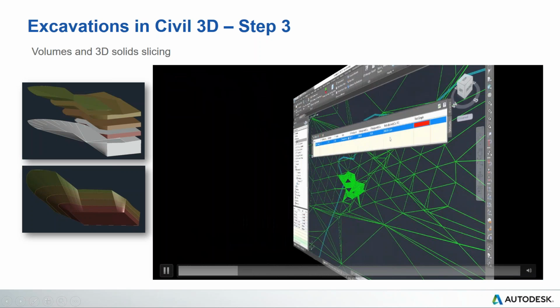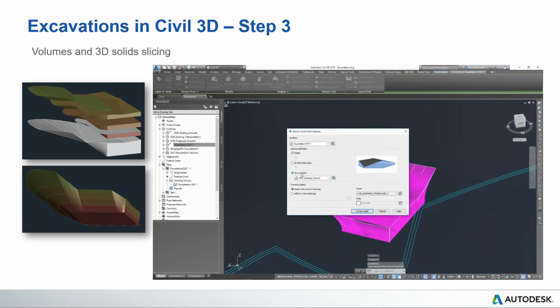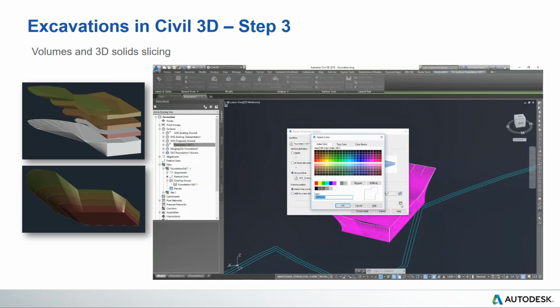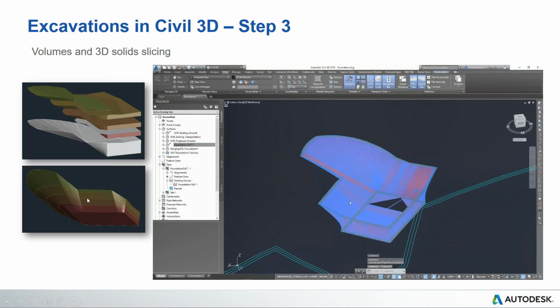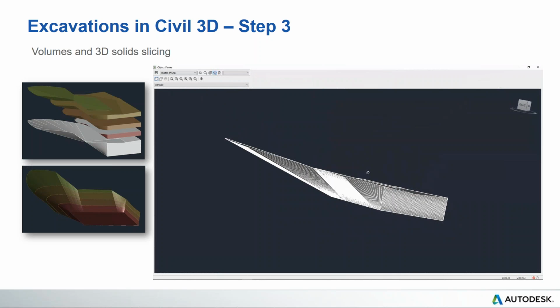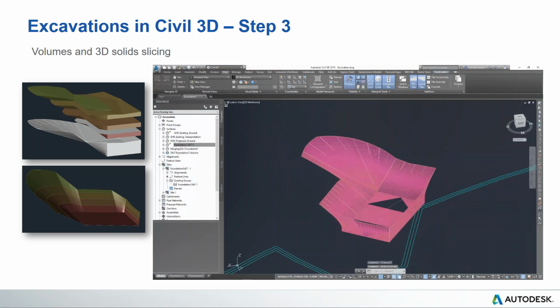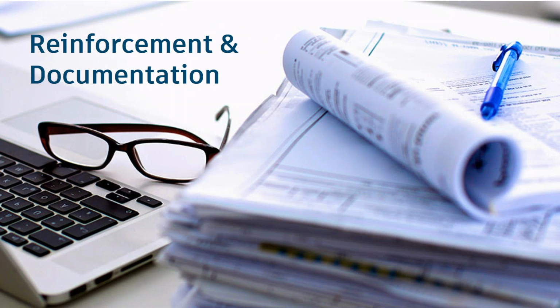We can also create different levels or different stages of excavating that foundation, whether it's based on the construction that will happen on site, certain construction requirements, or certain geological layers that we might have created using the geotechnical module, which basically runs on top of Civil 3D. So it's up to us as designers to decide how to split or slice this excavation and to what level of detail. We're done with the excavations in Infraworks and Civil.